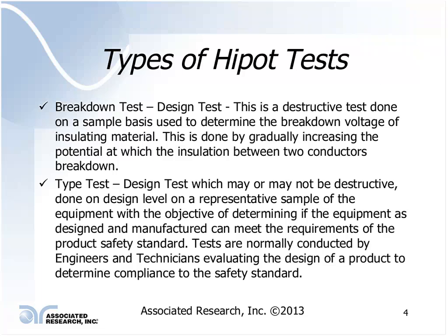Typically, the Hipot tester has to have a high enough output current capacity so the voltage does not sag once that arc is initiated, and you normally have a tester that has some type of meter memory that retains the actual breakdown reading of the potential that was applied when the sample failed.